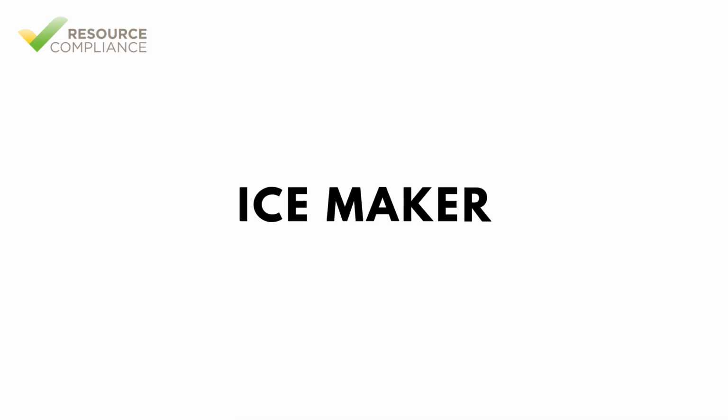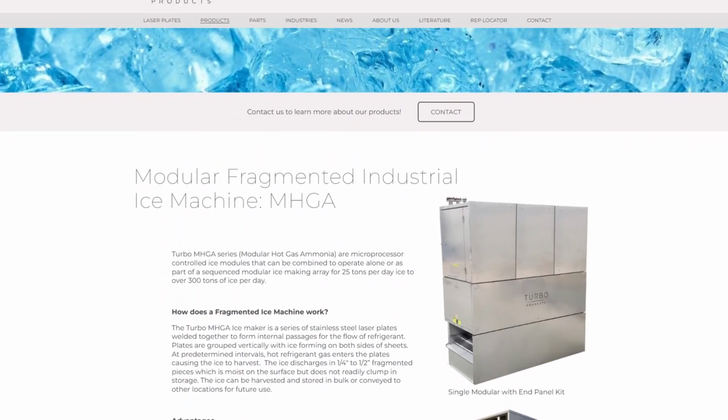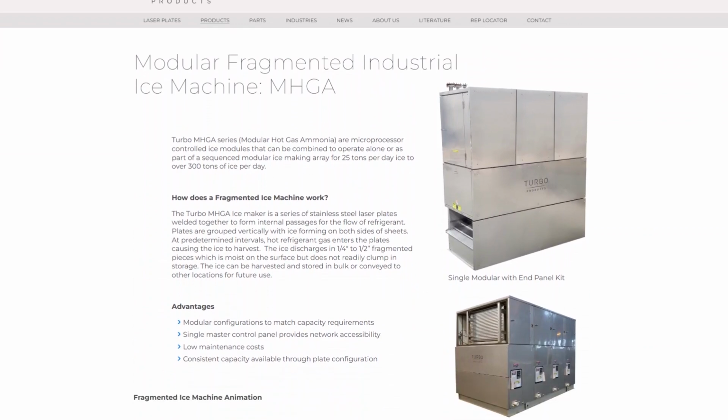An ice maker is an evaporator designed specifically to make ice that will be consumed. There are various types of ice makers, all of which use cold liquid refrigerant to freeze water. A plate ice maker operates using the same principle as a falling film chiller. Water is sprayed or trickled over vertical or inclined plates containing cold liquid refrigerant.